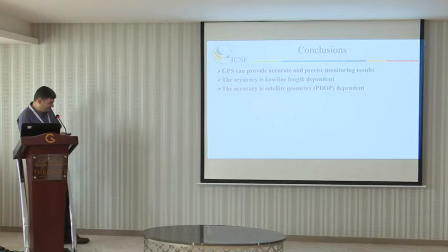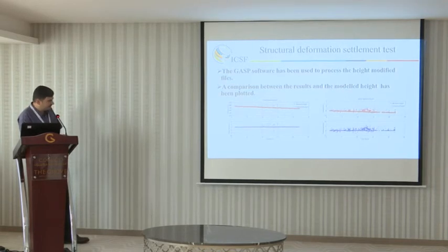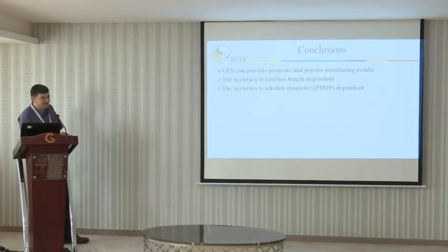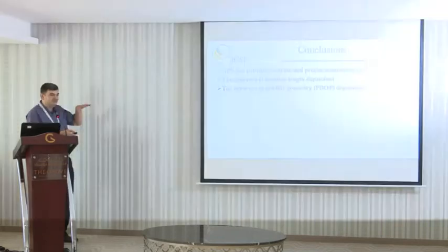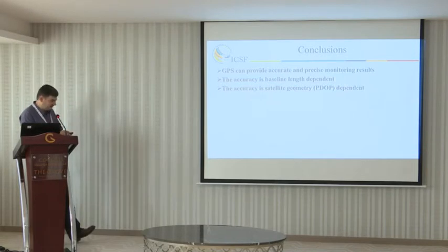Now, the conclusion is that GPS is very reliable equipment and tool to monitor buildings and constructions. The accuracy is baseline length dependent. And if you see here, we had some issue in this area. We did further investigation, and we found out that because of the geometry of the satellites, when you have poor geometry of the satellite, you get poor results.